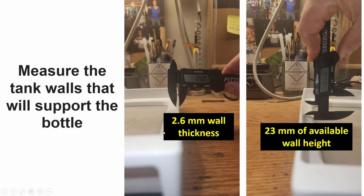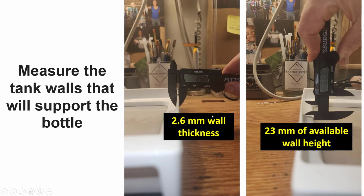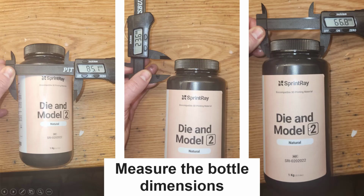And then we need to take some measurements. So I had a spare tank. I just measured the wall thickness here. So if you go back to this design, basically it just slides over the wall of the tray. And so I measured that, just took some cheap calipers, 2.6 millimeter wall thickness to your tank. And then I also need to check the height, because as you can see here, there's a limit to how deep you can go. And the measurement I got there was about 23 millimeters of available wall height.